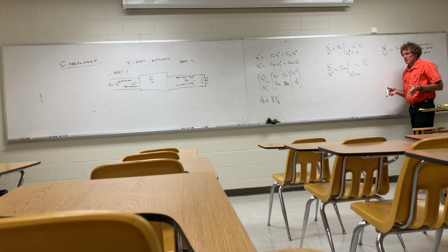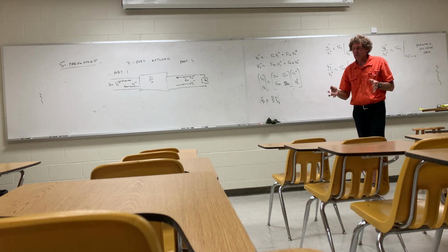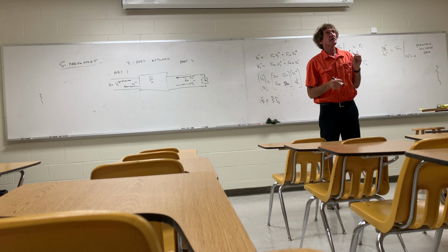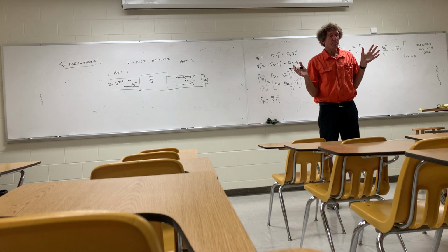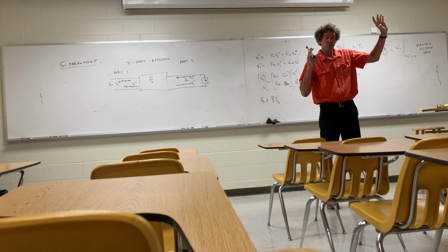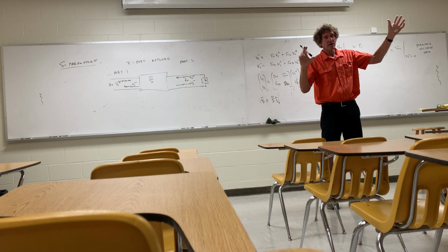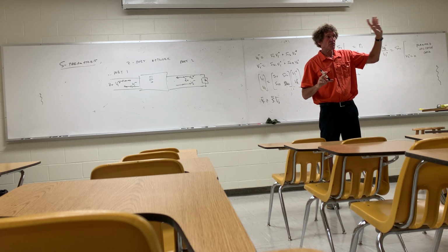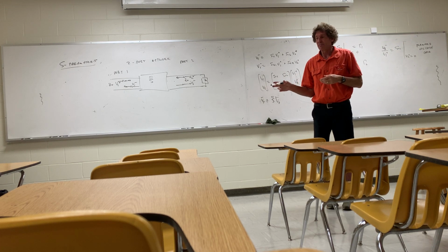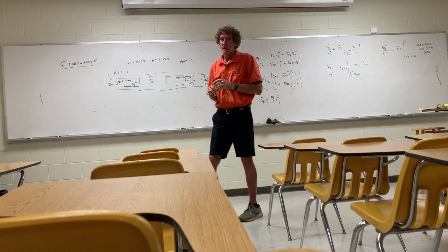Now, in high frequency engineering, if you're using standard bipolar transistors, they're current controlled current amplifiers by definition, but when you put the resistors and stuff and load it, then you can get a voltage controlled voltage amplifier. Just try to appreciate that. Generally speaking, bipolar transistors are current controlled.